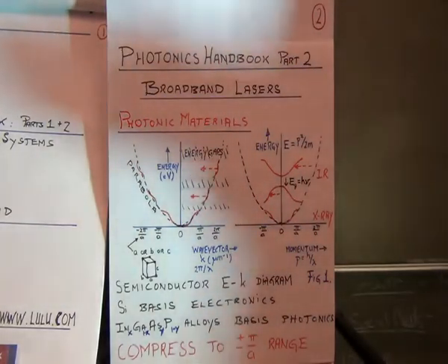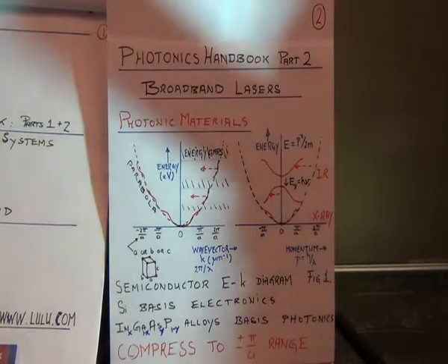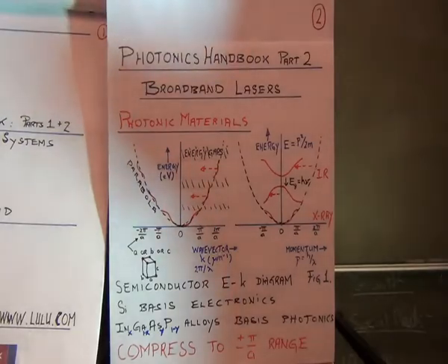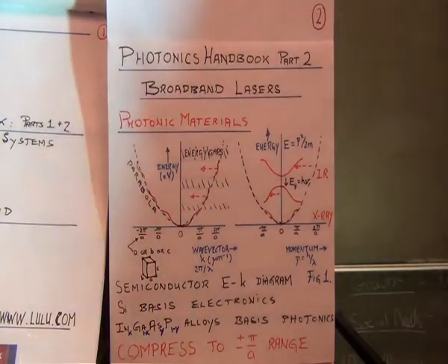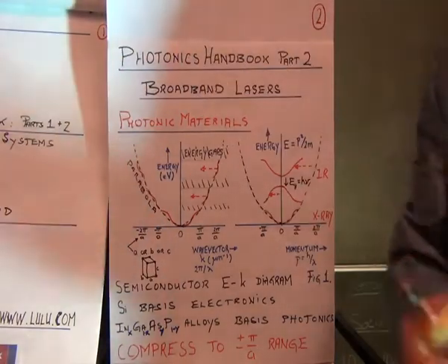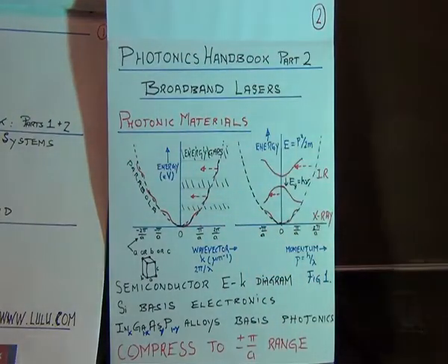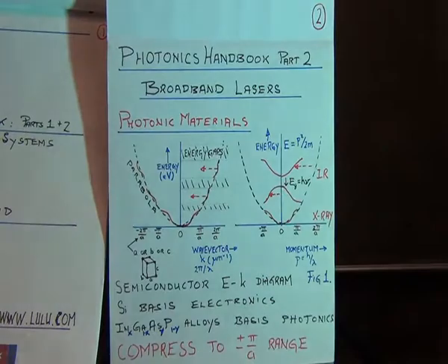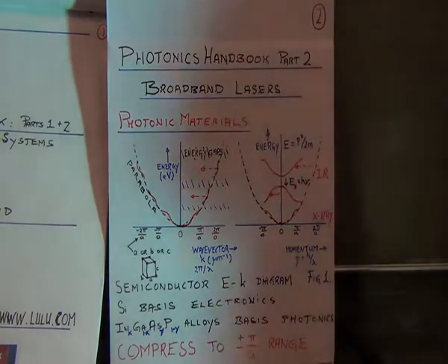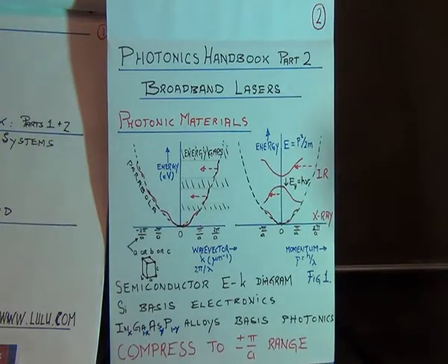If they could have used silicon, you see, they could grow a silicon laser on the same chip as the microprocessor and have it speaking to another microprocessor or to an optical fiber or to a communication link or whatever, all monolithically. But it doesn't work because of the band diagram of silicon. It's been necessary to find new materials, and they're listed there, which we call 3-5s.